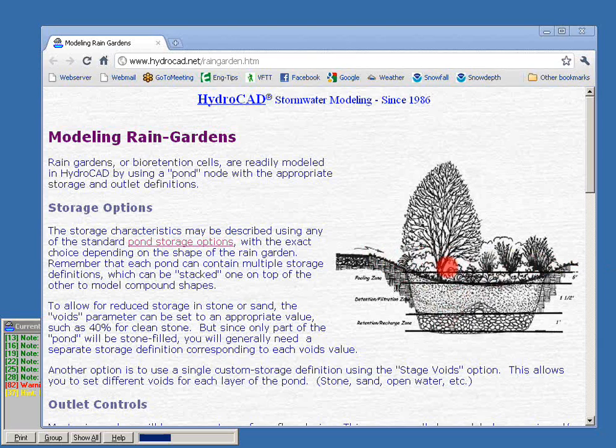Now, these layers take a large period of time, usually, for the water to infiltrate through the system. So again, we have to look at the analysis we're doing and make sure we're clear about whether we're modeling short-term peak flow effects or long-term water quality effects. It's not uncommon that you're going to need to look at these structures in two ways. You'll be building them so that you can handle perhaps a half-inch or a 1-inch water quality event.